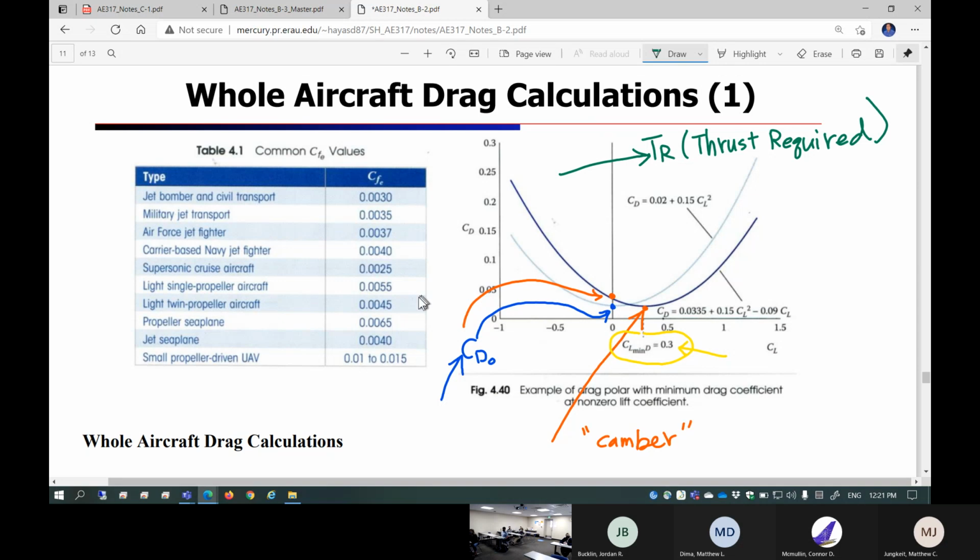And if you choose a bigger and heavier engine, that is actually going to affect the airplane back. That means the airplane is too heavy. You have to beef up your structure, which becomes even heavier, and then your CG point changes. Oh my goodness, this is not stable anymore. Okay, so that's all about trade-off, right?